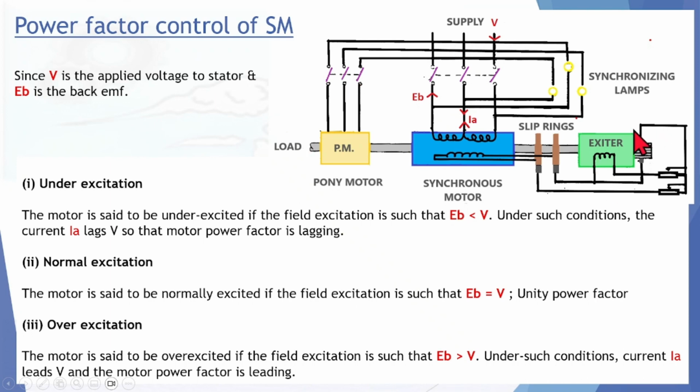And this is how you use a synchronous motor to control the power factor of a bus bar. We call this special device, when we use the synchronous motor in the application of power factor control, a synchro condenser or synchro compensator. Mostly you can see it in shaft generator systems which are thyristor operated. It's nothing more or less than the same synchronous motor or synchronous generator, where by varying your excitation you can change the power factor. And whenever in a normal synchronous generator motoring or reverse power takes place, the generator runs as a synchronous motor.